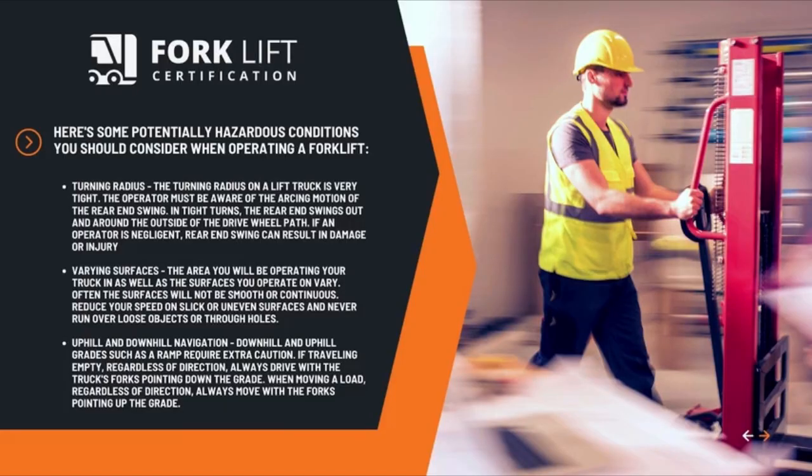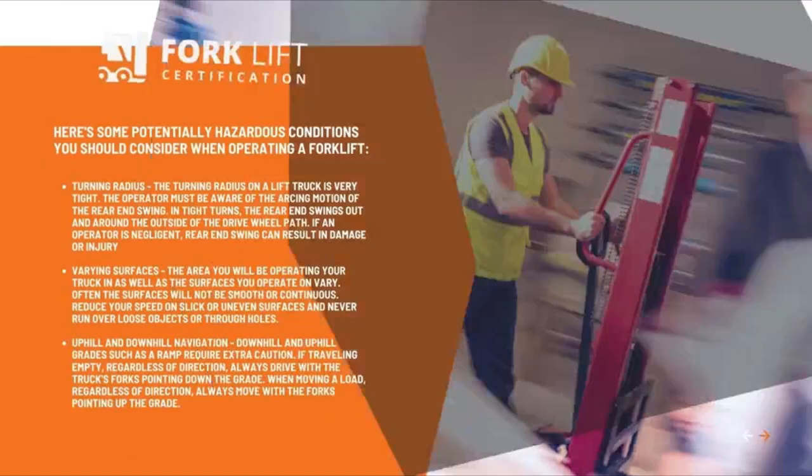Uphill and downhill navigation. Downhill and uphill grades such as a ramp require extra caution. If traveling empty, regardless of direction, always drive with the truck's forks pointing down the grade. When moving a load, regardless of direction, always move with the forks pointing up the grade.